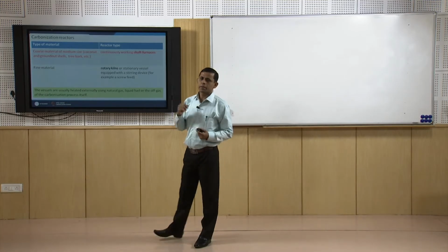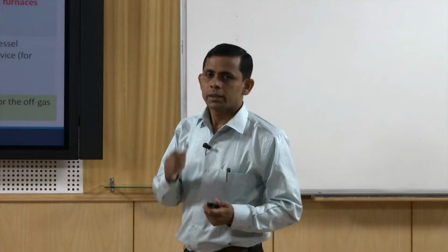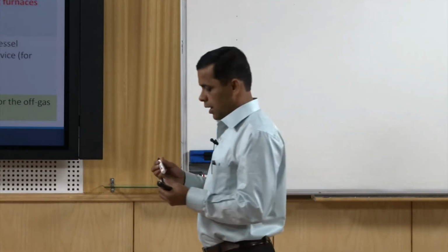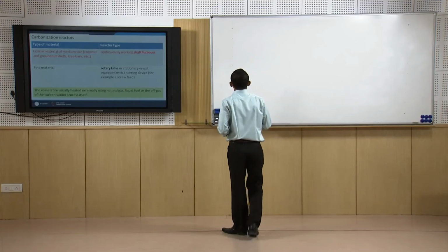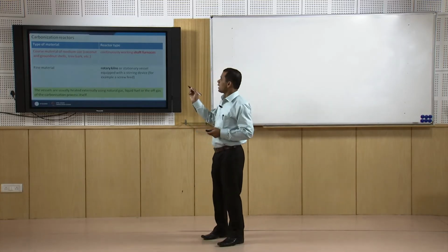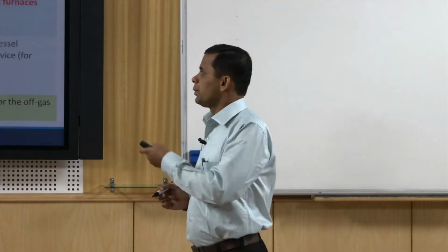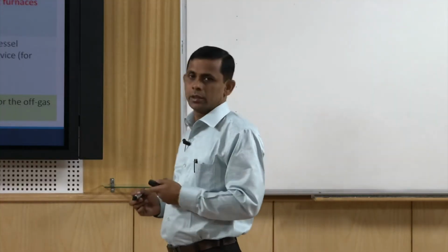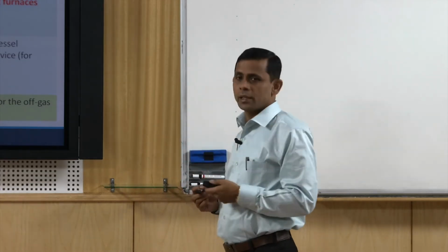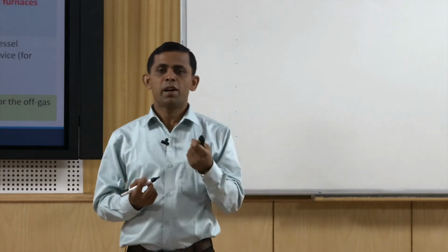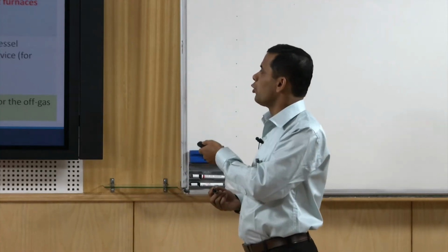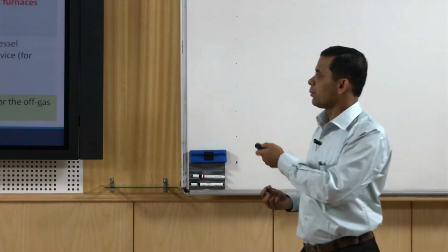Just now we discussed in the previous part of this module that carbonization is necessary to improve the fuel quality of the briquettes. For this purpose we have basically two types of reactor, depending upon the type of material. If the material is coarse, of medium size, then we go for continuously working shaft furnaces, and if the material is fine, then we go for rotary kilns or a stationary vessel equipped with a stirring device, for example a screw feed.